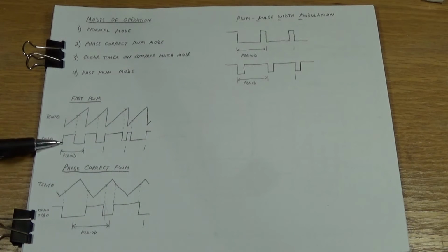And there's a couple of modes that you can set the I/O pin to. There are 4 different modes, and 2 of them are what I just described here. But the other mode is to invert this pin, so that it would be high at this point and low at this point, and high here, low here, etc. It would just be the exact opposite phase of this one.